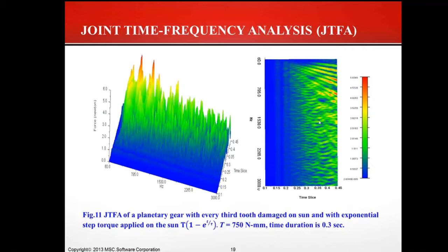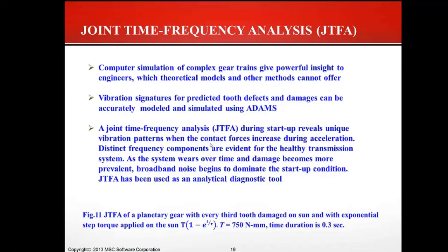So this is one pattern. If we want to look more, we can damage more teeth and see how it changes. Now this kind of technology, joint time frequency analysis, is applied in rotor dynamic systems and rotating machinery in industry. But this is our first time to simulate it for the gearing system.